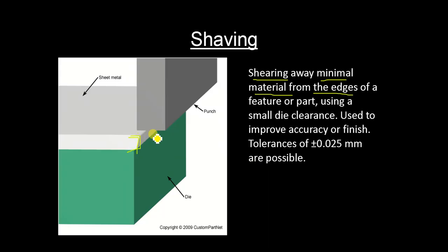In those cases we utilize the process of shaving, trimming out a certain amount of material from the edges, and the material removed is very minimal in thickness. Clear? In comparison, in the shearing process we are literally cutting the material into halves, or the desired lengths as per the requirement.